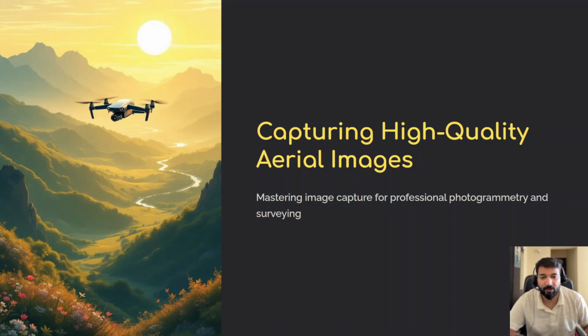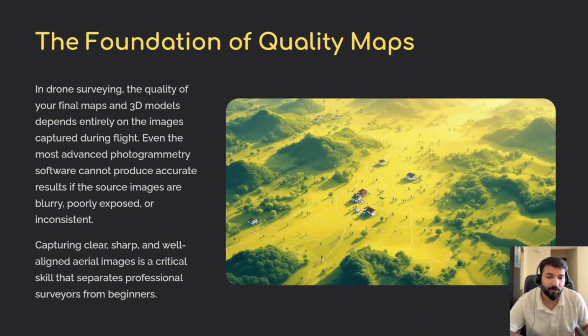Welcome to the next lecture on capturing high quality aerial images. In drone surveying, the quality of the final maps and 3D models depends heavily on the quality of the images captured during the flight. Even the best photogrammetry software cannot produce accurate results if the images are blurry, poorly exposed, or inconsistent. That's why capturing clear, sharp, and well aligned aerial images is a critical skill for every drone surveyor.